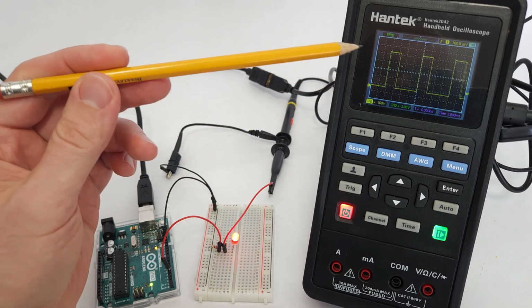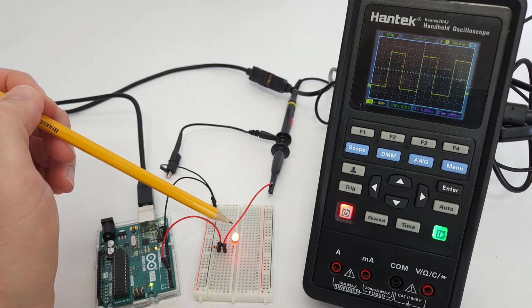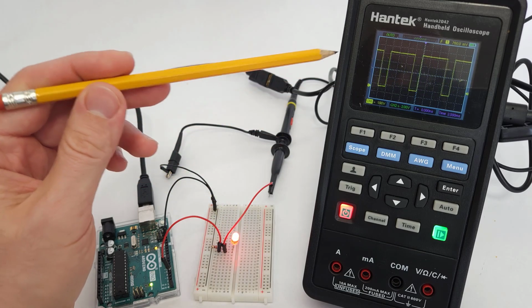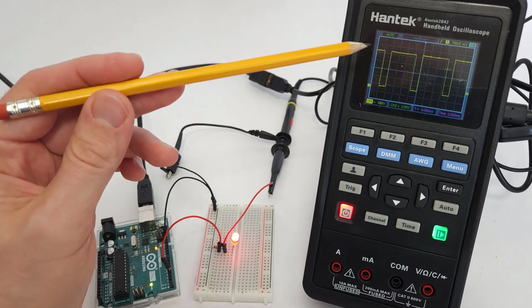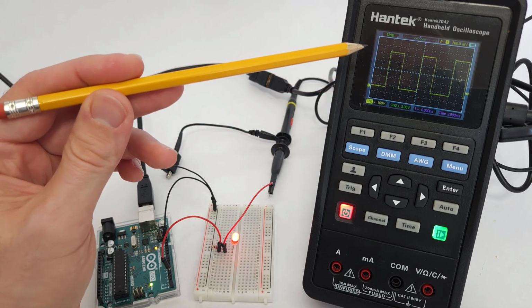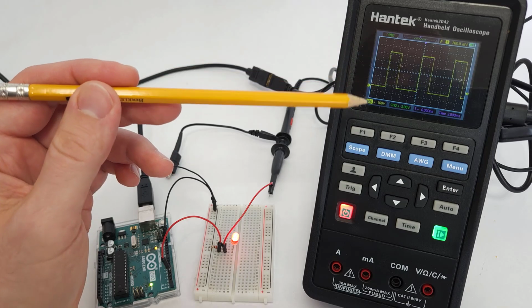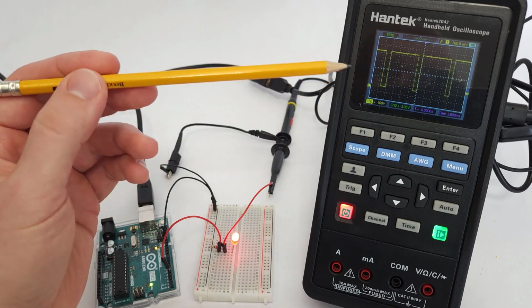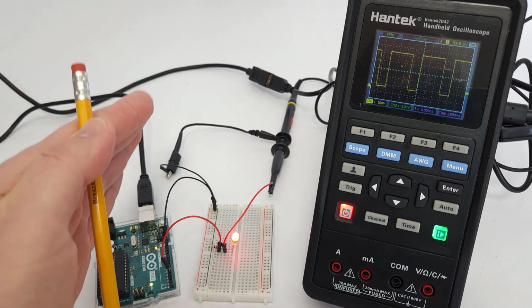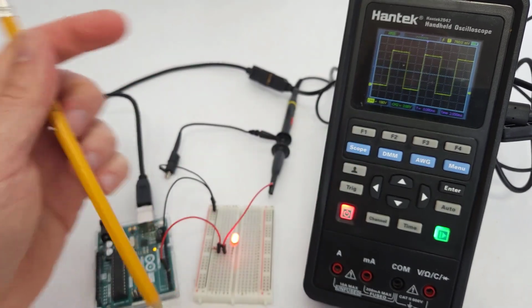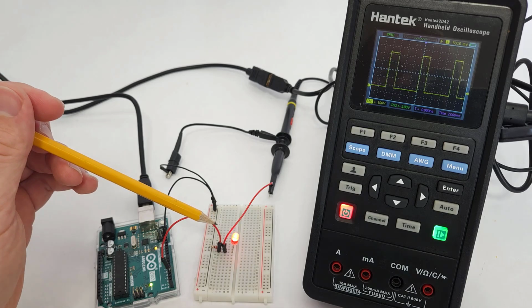You can also use this exact same concept to control the speed of a motor. Rather than using an analog voltage to adjust the speed, you use a PWM signal, for example, to have the motor on half the time and off half the time, but as long as the frequency of that signal is fast enough, we're not actually going to see the motor start, stop, start, stop, start, stop. It's just going to spin at a lower speed.